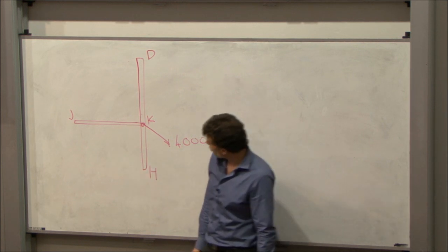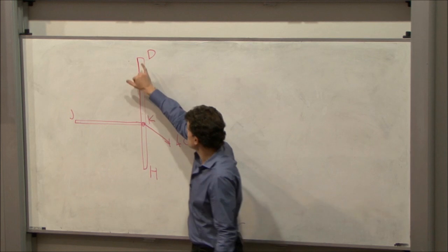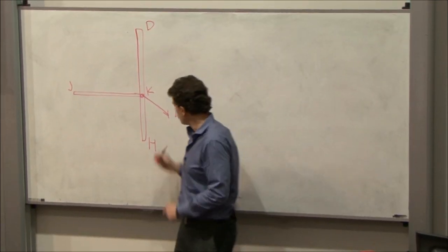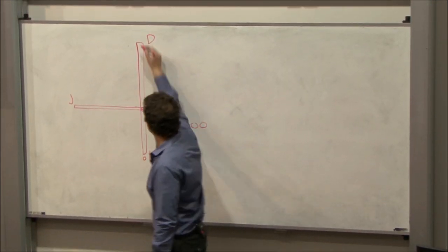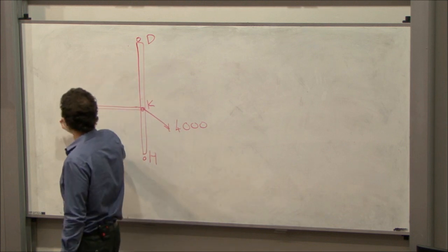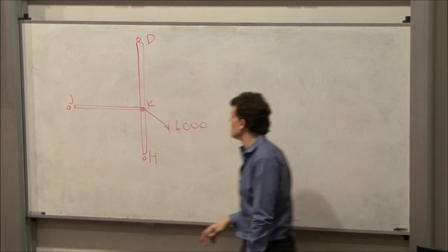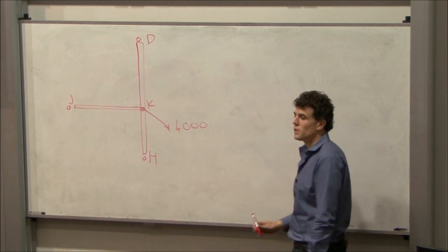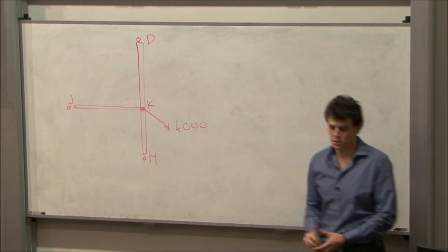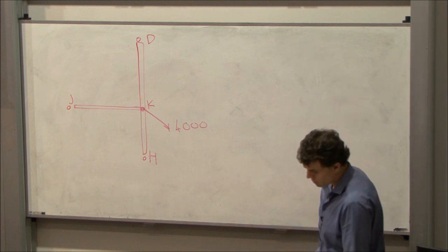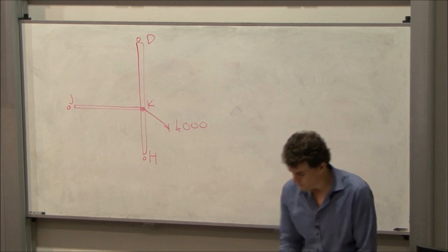Now what we also know is that at the ends here there's nothing else to carry load, so the boom loads at the end here have to go to 0. So there's no forces hanging off the end. So how do we maintain equilibrium on this? Well, we maintain equilibrium with the leftover shear flows that are there.